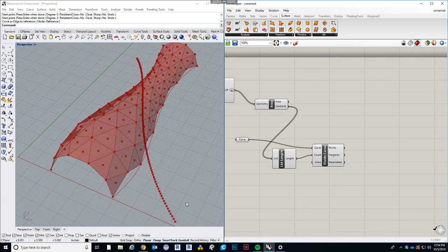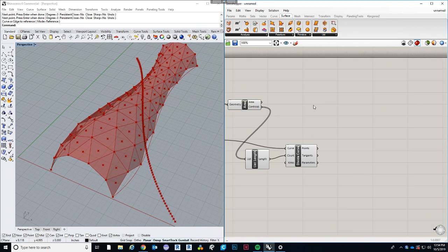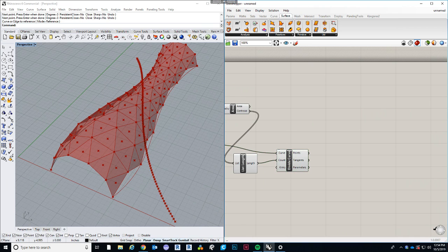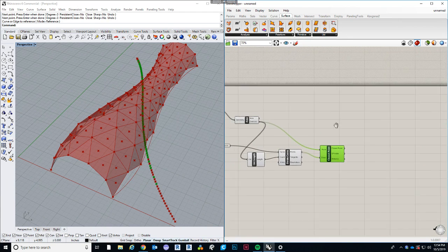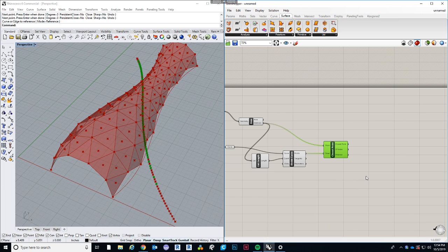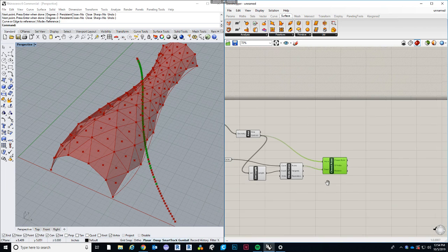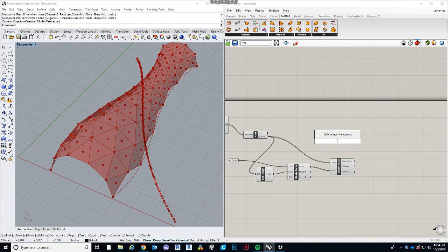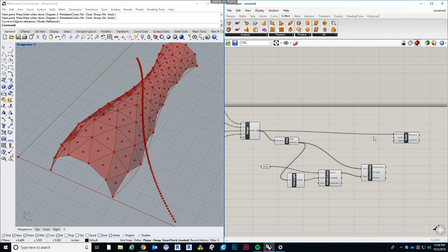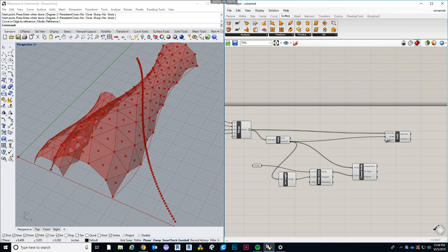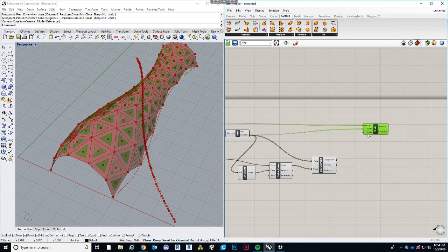Now we have a curve that's divided same number of points as the panels, and then use closest point, not points, but point, and take the centroid and the points, and then all right, well, now we have the closest points and their distances. Let's use scale as our transformation that we want to make an attractor for. So we'll want to take the panels, plug that into the geometry, take the centroid and use that as the center of the scaling. And then we need a factor.